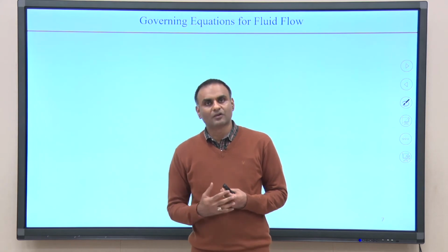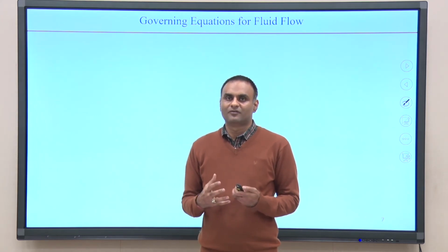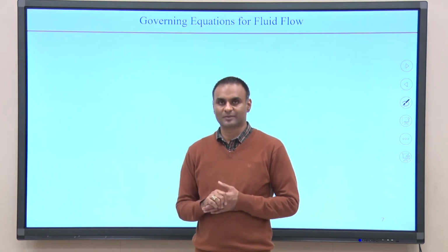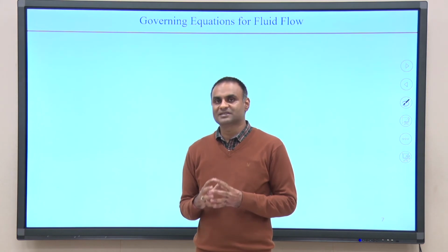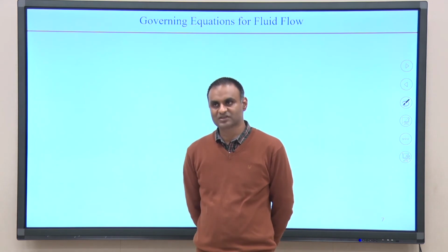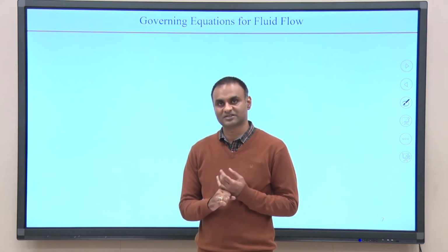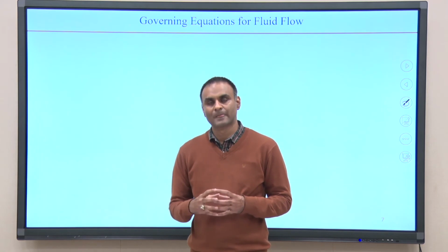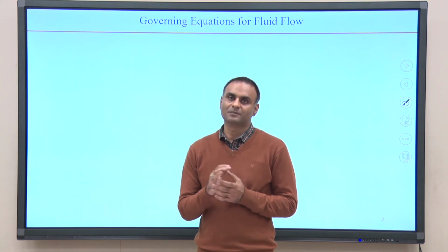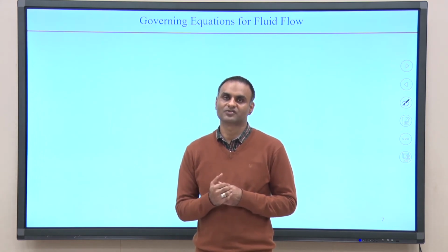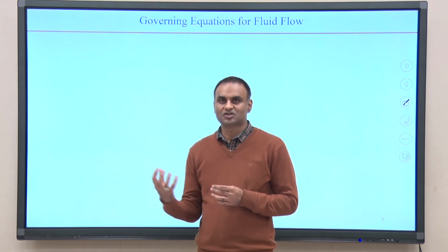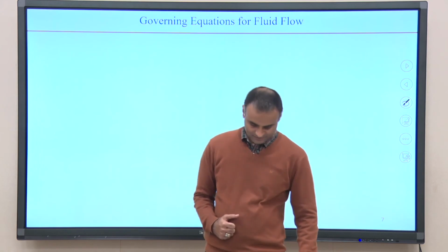What we are going to do now is look at the fundamental governing equations for fluid flow, for an isothermal flow, and try to non-dimensionalize those differential equations, which are called Navier-Stokes equations. So, the goal is that we familiarize ourselves at the start of the course itself with the Navier-Stokes equations, and at the same time we non-dimensionalize them and see that the dimensionless groups appear naturally when we non-dimensionalize these equations.